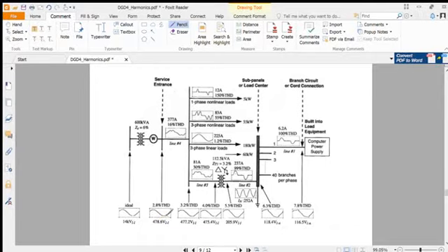So here a harmonic factor is included, and the shape gradually changes, as well as the voltage getting reduced, because this is a step down. The harmonic power increases for the second harmonic, third harmonic, and as we go to the higher orders the amplitude goes down. Then there are three nonlinear loads for the three-phase system.